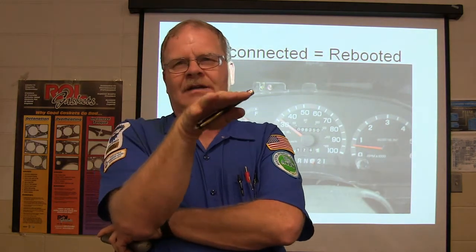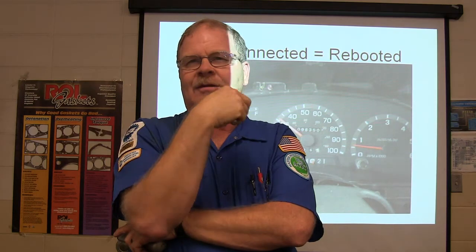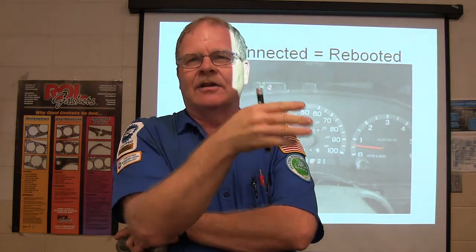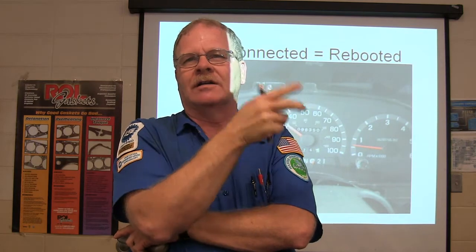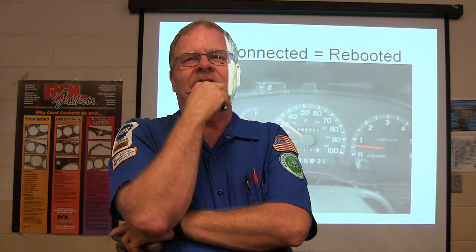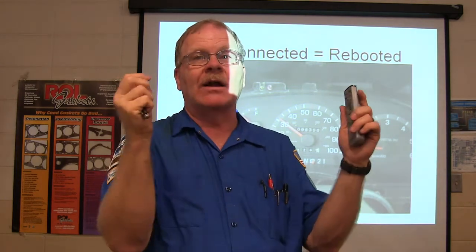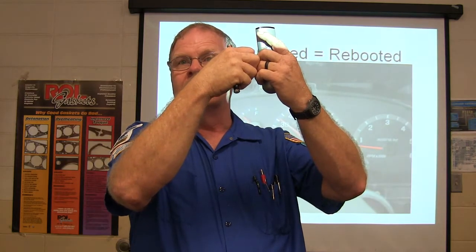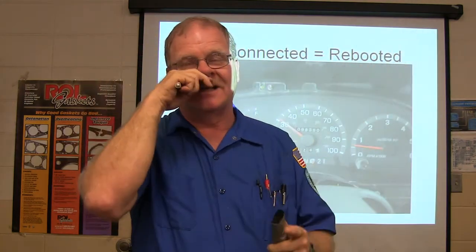It's like rebooting a computer. Now, you remember I was telling you about some of the Dodge Caravans, and I've actually had people send me emails through my website. They'll say my Dodge Dakota is doing this, that, and the other, the speedometer's gone dark, and the door locks aren't working. And I'll say, this won't cost anything. What you need to do is disconnect both battery terminals, hold those things in your hands, touch them together, and let it bleed all of those capacitors down so that you're basically rebooting everything, and then put it back together.